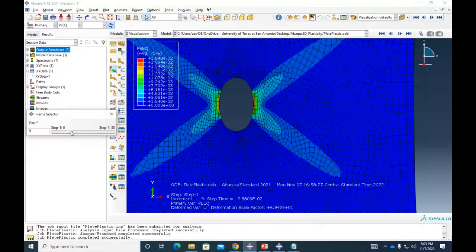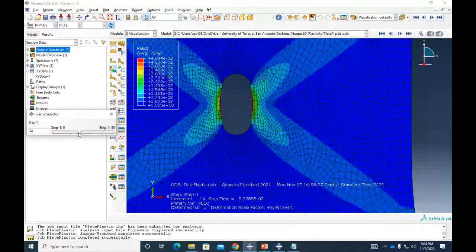So I'm giving you finite elements in a different way, not focusing on the modeling, right? Because I know that each one of you is capable of eventually getting it done in terms of creating a complicated shape. But what's important is how to add the physics, how to add the plasticity, how to post-process the information that Abaqus is giving you. Because if you input trash, you get trash, right? So we want to be smart users and not only add some crazy properties and get our result. We want to really get a good insight about the problem.